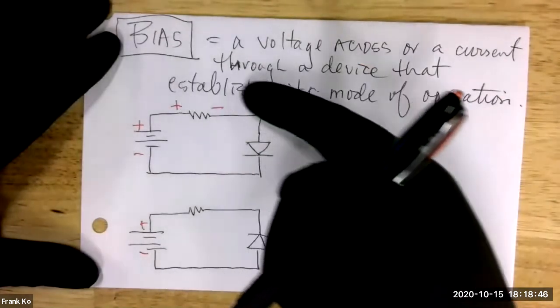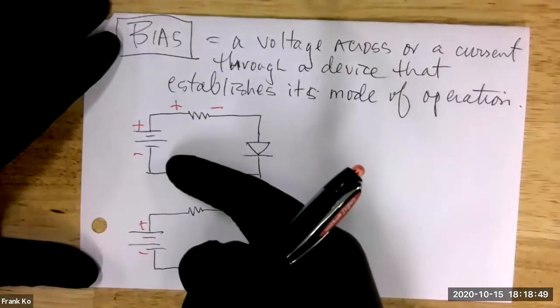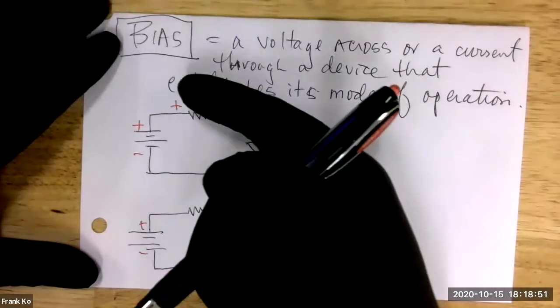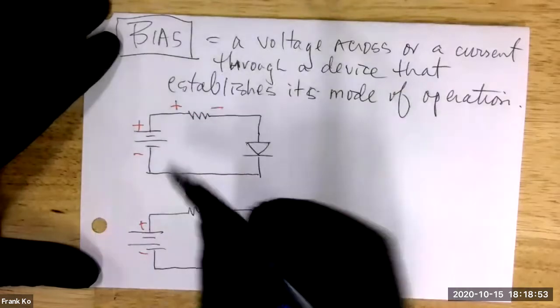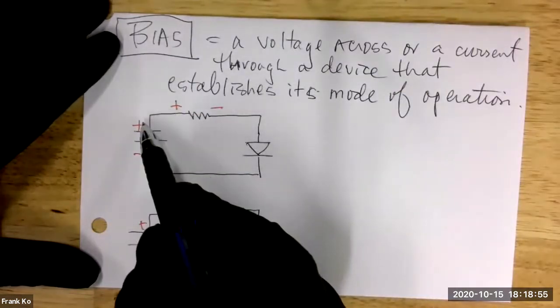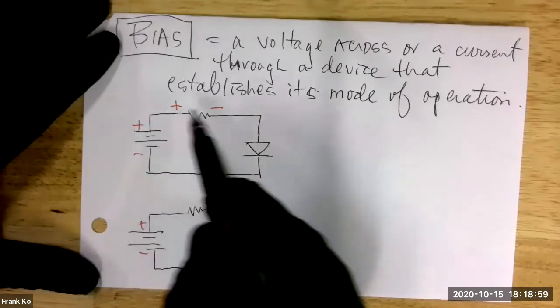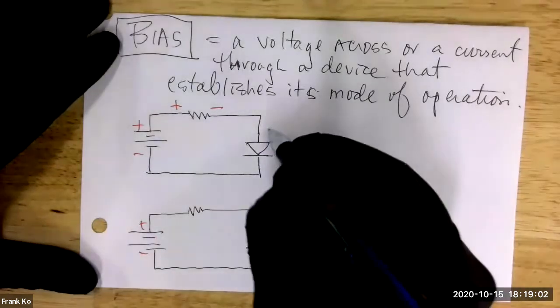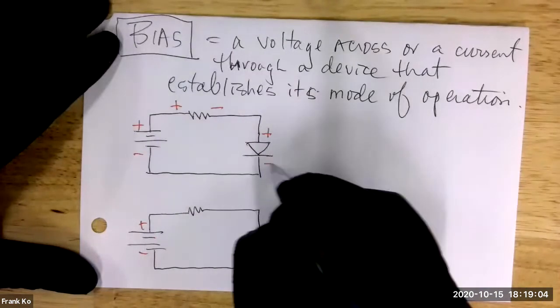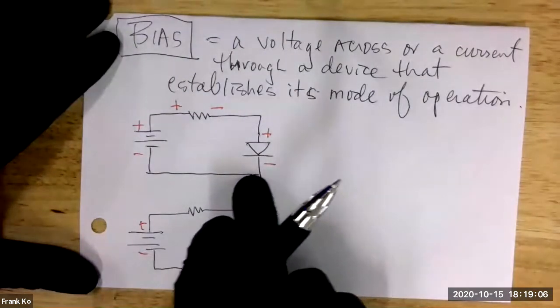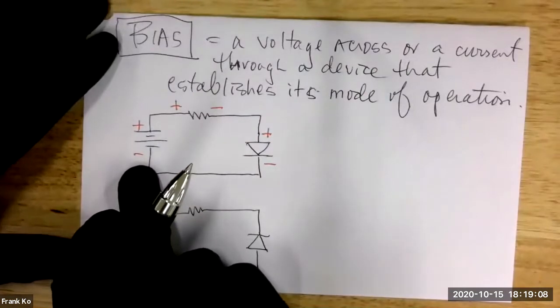And that starts the pattern of the polarities around this upper circuit. So it starts off positive, negative, and the reason why it's positive is because it's physically attached to the positive side of the source. This side is positive, this side is negative, then this will be positive, then this will be negative, and do I have negative attached back to the negative side of the source?